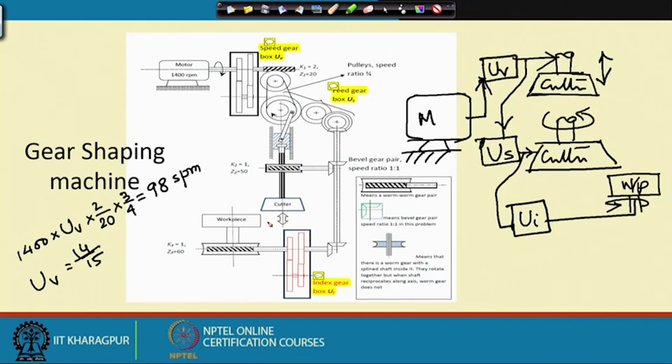So, the rotation of the cutter, suppose I set it to be say 0.25 millimeters per stroke of the cutter, just like feed motion on the lathe per revolution of the job. So, here per stroke of the cutter. If I set this, how are we going to solve it? So, let us start from one stroke of the cutter.